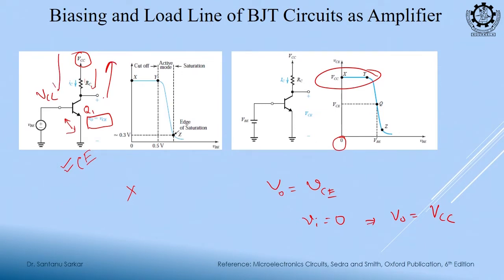If more current is flowing through this, it should go in the opposite direction, right. The drops you are subtracting. What is your output? KVL, VCC minus the drop, that is your equation. So, if this goes up, this goes down. If I goes up, this goes down. They are inverse because of this minus sign. So, you see now your input is very high, output is 0, agree.